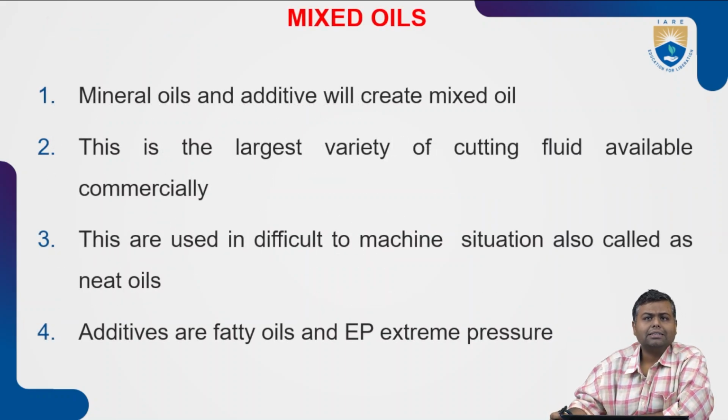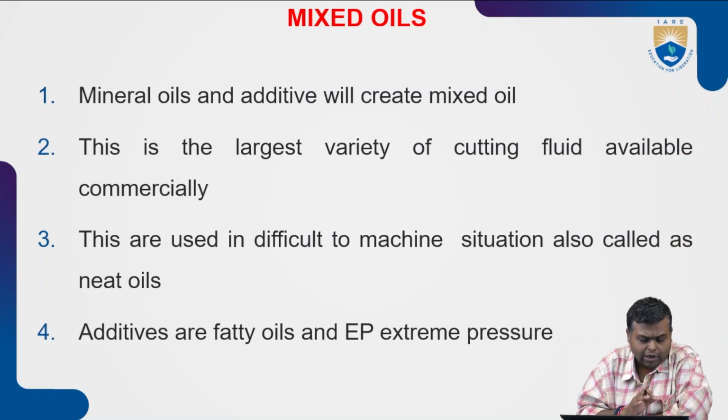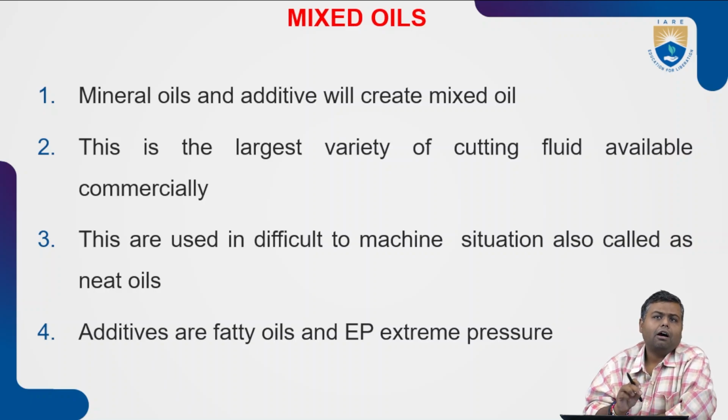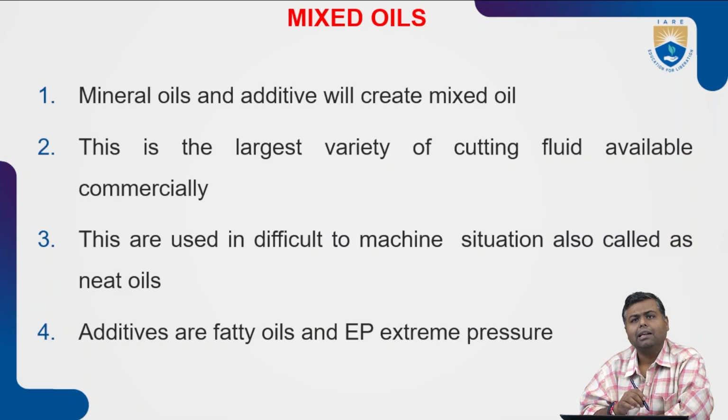Mixed oils are generally two different types of oil. You have mineral oils plus some additive mixture. So, mixed oils are created by pure mineral oils plus additives to the mineral oils. This is the largest variety of the cutting fluid available commercially.